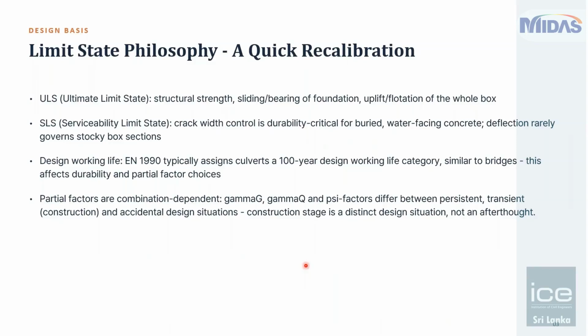Deflection rarely governs these stocky box sections, but still is among the SLS checks. Design working life of box culverts is defined in EN 1990 and is defined as 100 years design working life category, similar to bridges. This affects the durability and partial factor choices.